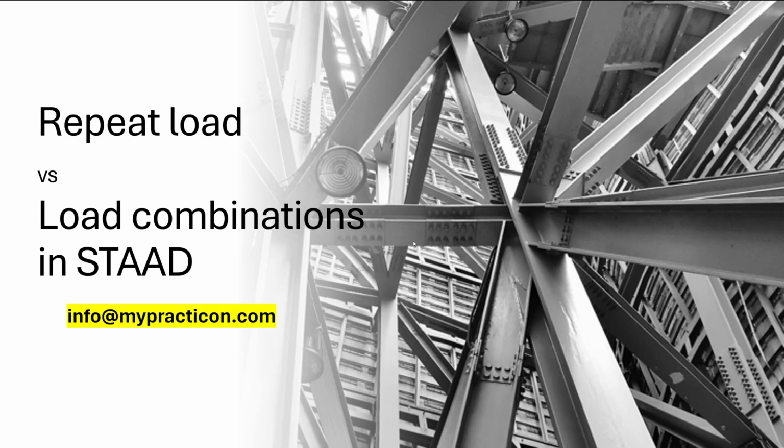That means when the structure is loaded with self-weight, we may get wind also, we may get seismic force also, or any other live loads will be acting onto the structure combinedly. So initially the structural engineer will derive the primary load cases like dead load, live load, wind load and seismic load, and finally these need to be applied together with the combination of factors recommended by the standards.